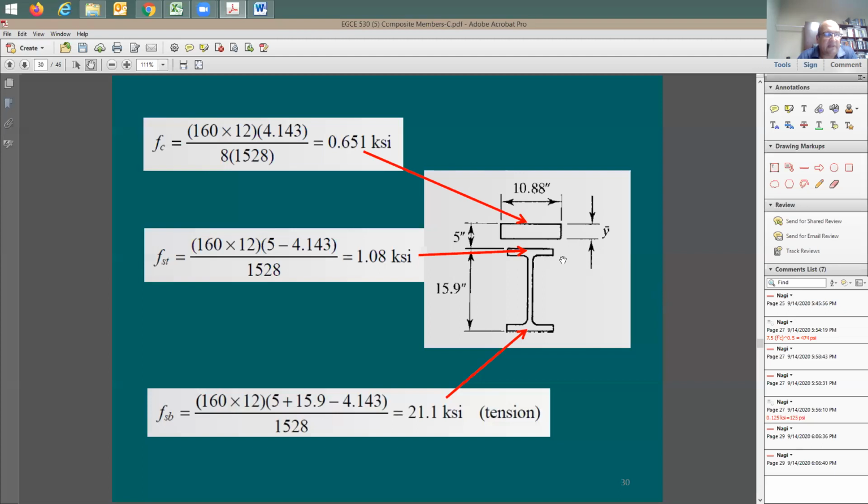And in some cases, you may have the neutral axis through the concrete, and at that point, we can have this discussion. Should we ignore this part of the concrete to be in tension, or we should just consider it as long as this maximum stress in the concrete is going to be within the cracking stress? There's going to be a little discussion here. But yeah, here's the method. You should be able to figure out the stresses, and based on this stress, you should be able to find out whether this section is still in good shape or now it is failing.